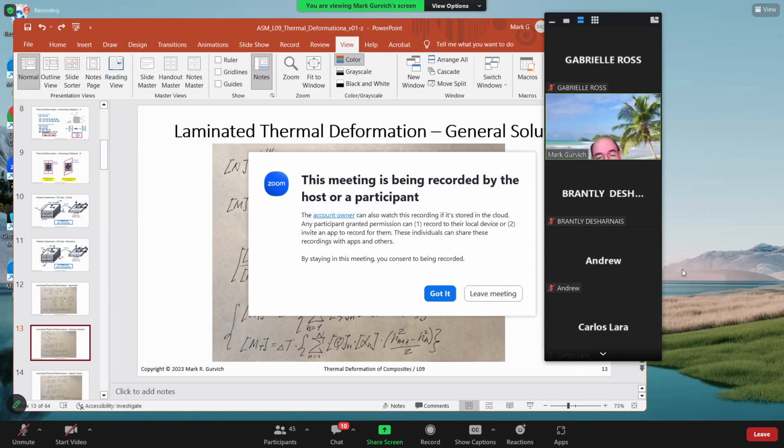So matrix N and matrix M are proportional to the matrix strain and the neutral position and bending with this ABD matrix. This matrix is symmetric, and A is the in-plane stiffness, D is the bending stiffness, and matrix B shows the effect of imbalance between them. So this portion is exactly the same as what we had in classical laminate theory based on this integration. But now we have an additional component here.